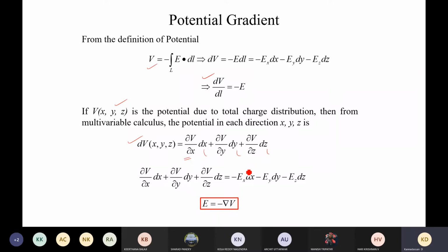This also tells about how, in a given short distance or a short space, the potential distribution is available. This is all very much useful for many computational applications. For instance, if you want to design an antenna, or a mobile phone or something, then you have to calculate the electric and magnetic field just around that. So we need to use computer simulation code. And in that simulation code, if we know the potential distribution, we can easily calculate that.